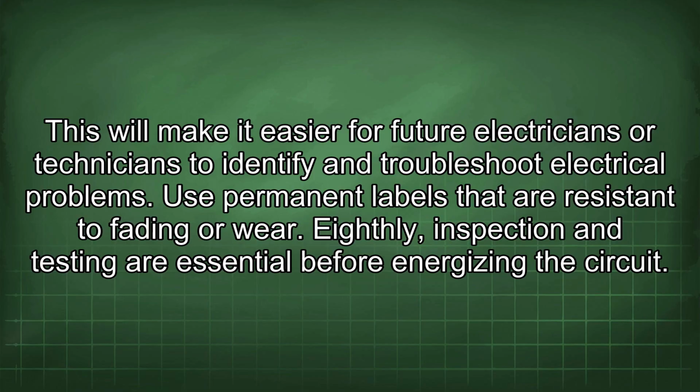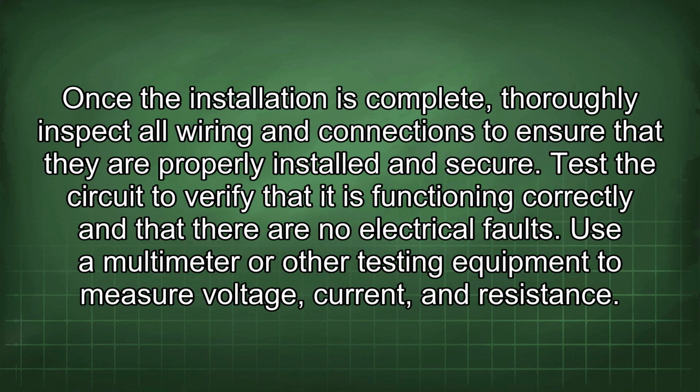Eighthly, inspection and testing are essential before energizing the circuit. Once the installation is complete, thoroughly inspect all wiring and connections to ensure that they are properly installed and secure. Test the circuit to verify that it is functioning correctly and that there are no electrical faults. Use a multimeter or other testing equipment to measure voltage, current, and resistance.